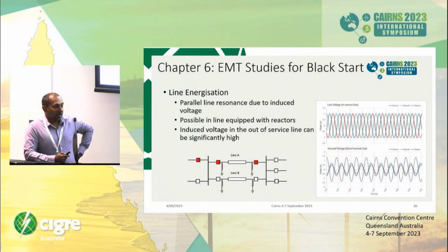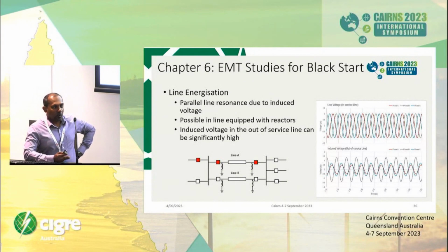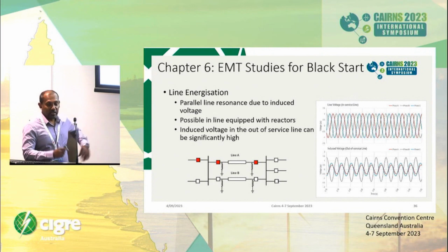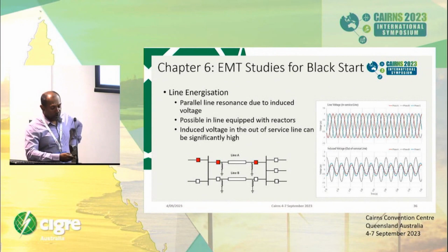But having said that, I have to remind you, it has happened a few times in power systems. I'm not saying exactly 50 hertz, that's a disaster situation, but if it's close, you can see very large induced voltages on the second line, even though it is completely de-energized from both ends and it's just a capacitance and inductor, due to the coupling from the first energized line.